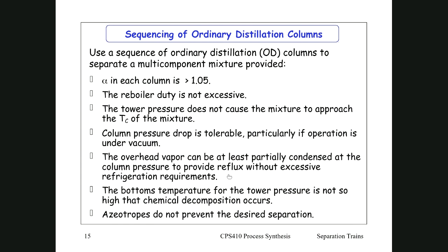And then if you have, for instance, oxygen or nitrogen that is dissolved in the feed as it comes in, that would be taken off as a small vapor stream off the top of the partial condenser. But the ethylene would be your product, and that would come out as liquid ethylene.